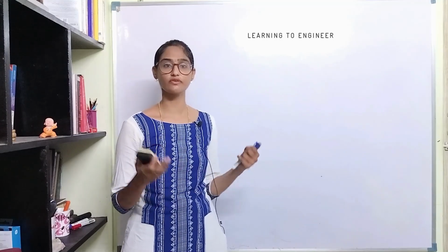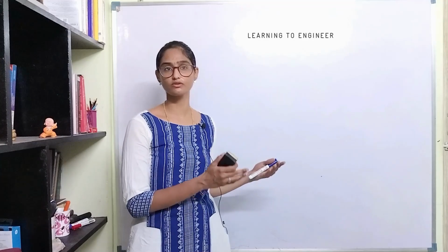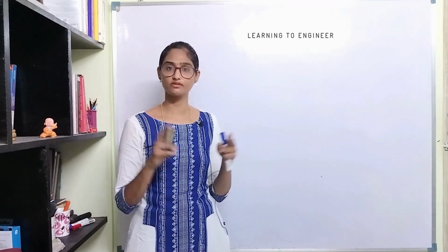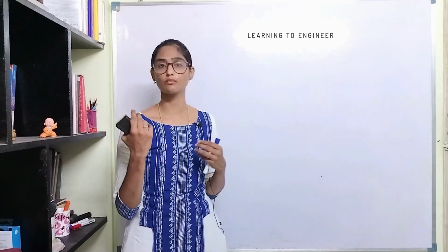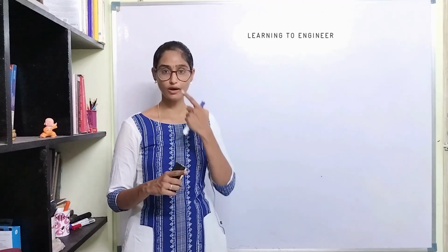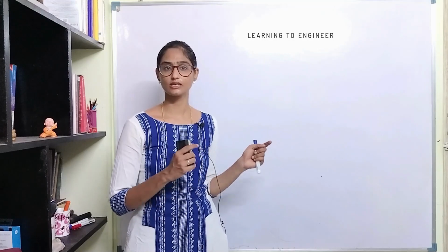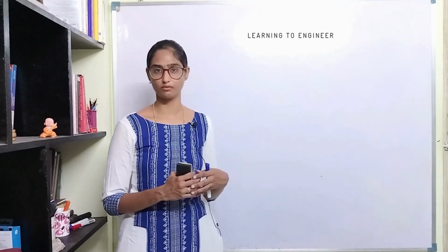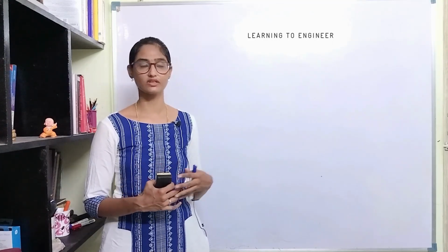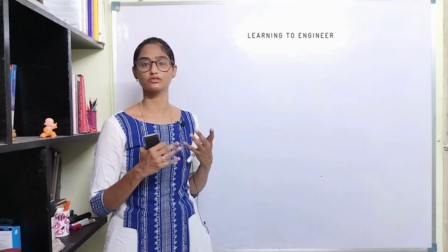If in a problem you find that LM741 IC is used for this circuit, so find out the value of this from what is given. So when you are finding the word LM741 or any specific model of op-amp that is given to you, you should understand that this is a practical op-amp and you cannot apply all the ideal op-amp characteristics in this problem. Okay, so let us see the practical aspects of an operational amplifier. We will also look at the data sheet of an op-amp and understand the different parameters that is associated with it.